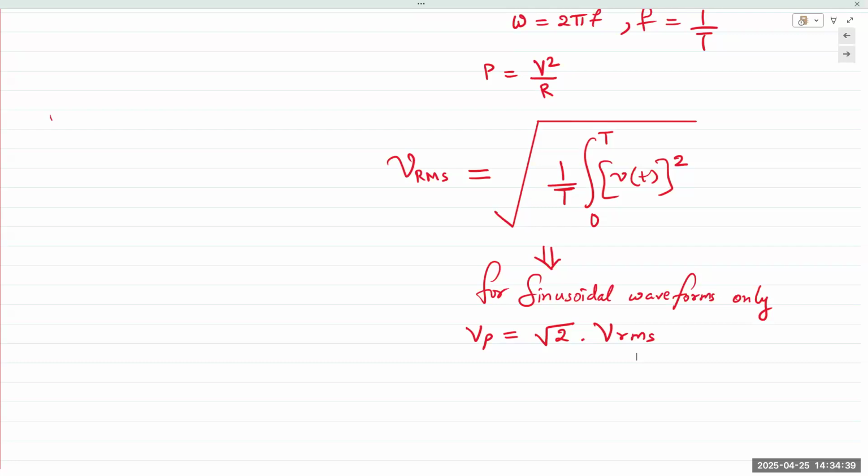So if you have calculators, perform that calculation and let's see what you obtain. 120 volts RMS times root 2, almost 1.5 times. And then double that answer and you get a peak to peak value of the power outlet.